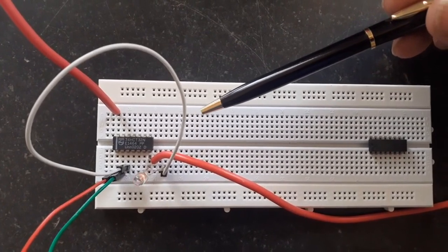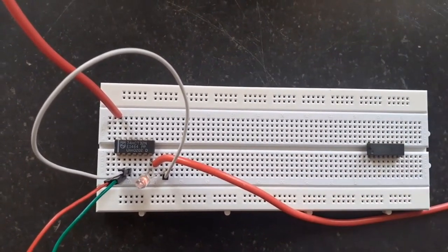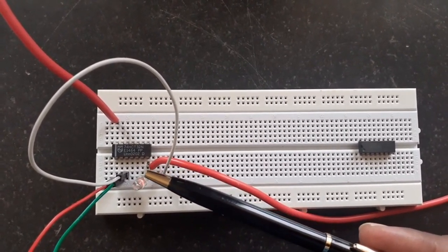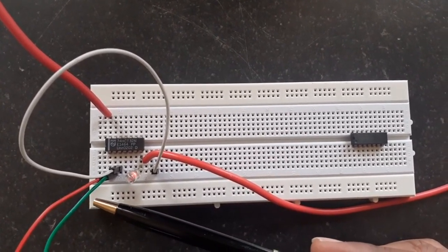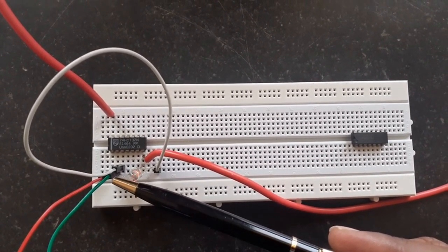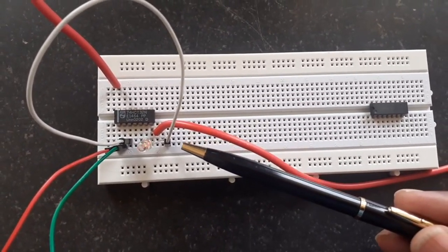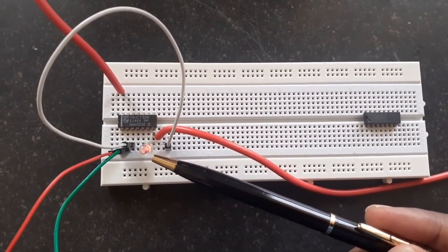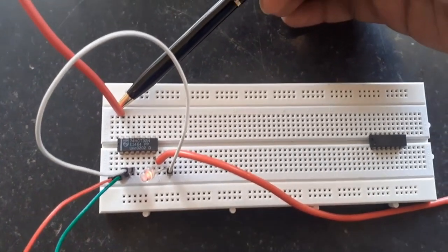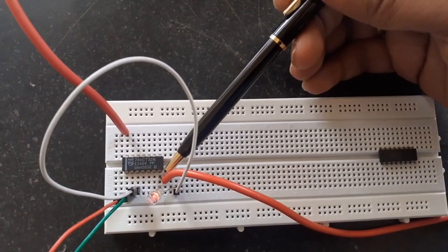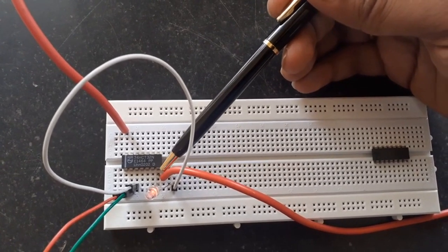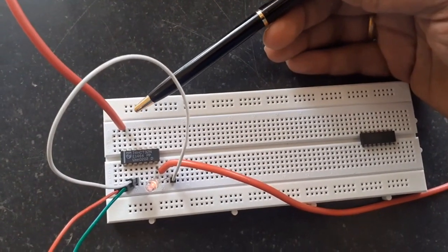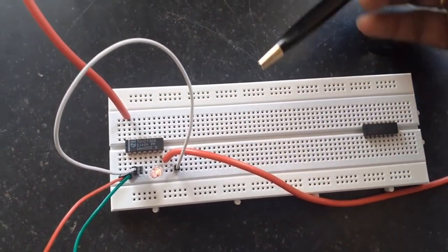This is the IC of the OR gate, that is 7432. Here at the lower terminal we have 7 pins, and the upper terminal we have 7 pins. In the lower terminals, 1 and 2, that is red and grey, are the inputs and white is the output, and this white is connected to the positive terminal of the LED and the negative terminal of the LED is connected to the 7th pin. For the power supply, the 14th pin is connected to the positive of the power supply and from the 7th pin we are connecting to the negative of the power supply. Here we are supplying 5 volts to the positive and negative terminals of the IC.